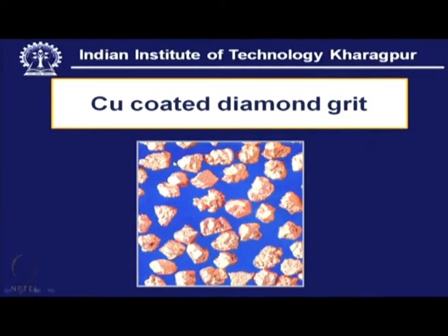So, this is actually dry grinding. This is a polycrystalline diamond, which has good microfracturing characteristics, always keeping the grit material sharp, holding the force and temperature within a control limit. Now, this dry grinding is essential for this grinding of carbide. However, during grinding, temperature may rise, and this diamond is also sensitive to this temperature. There could be some thermal degradation of this diamond. So, in this case, this coating of copper is used as a heat sink, which can conduct the heat from the grinding zone, and that will be accumulated in this sheath, which is a film of copper.